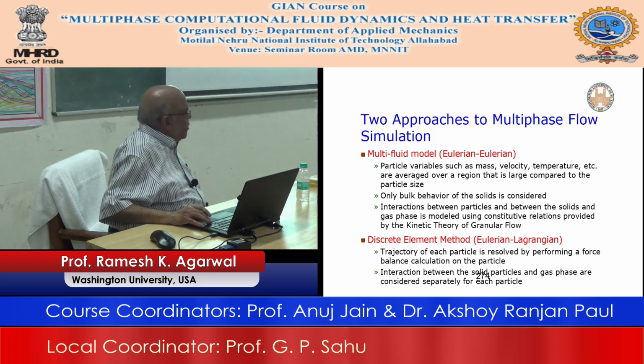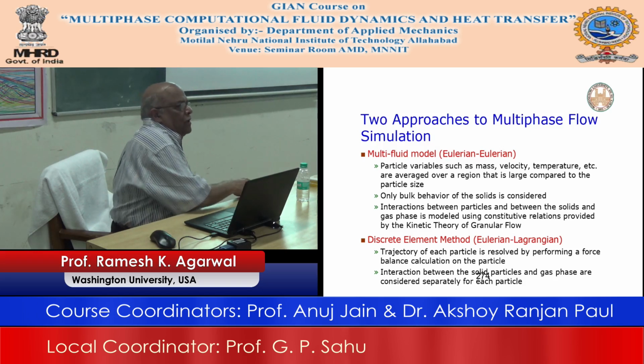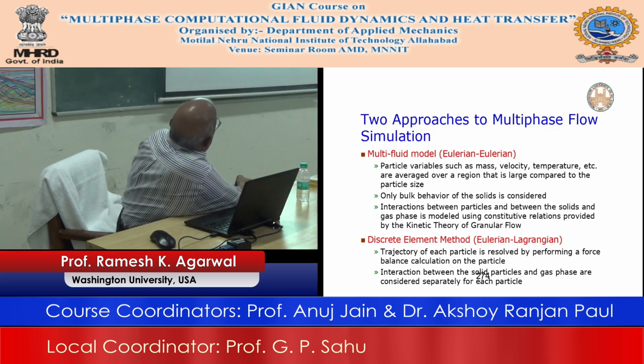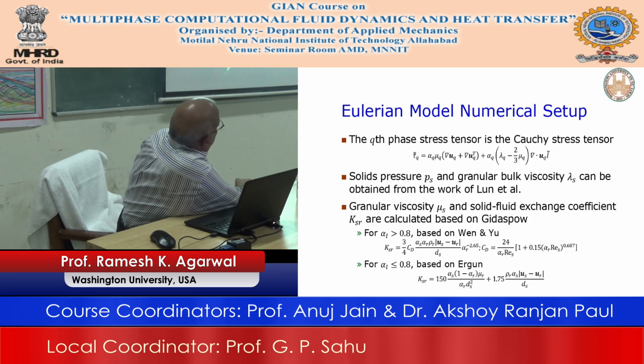All right, so we have already talked about these two approaches, DEM and Lagrangian. This is the equation that we are solving, and these are built in Fluent. Fluent has all these equations in it, okay? There are two phases, written in general form: phase Q and phase P. P is particle and Q is the liquid.